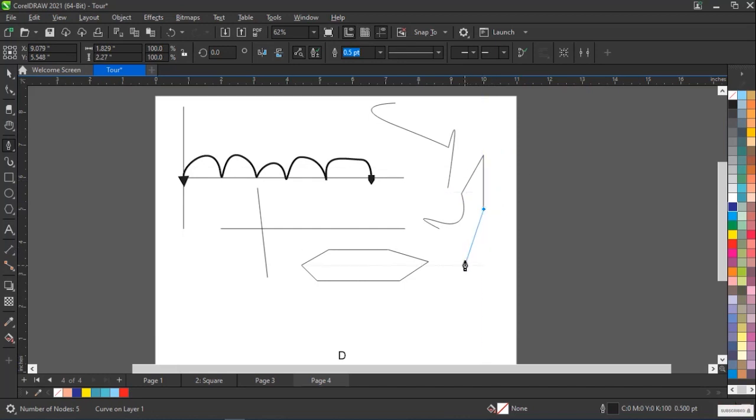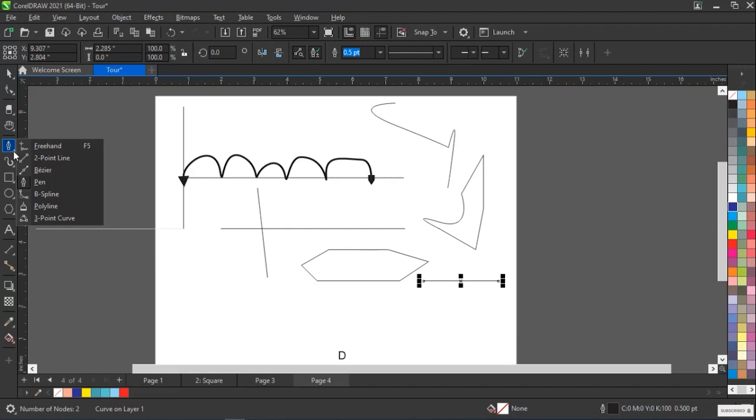Now the difference between this pen tool and the Bezier tool is just when trying to use a Bezier tool, you don't see the line. The lines you're making are not visible, but pen tool will have to show you the line and the direction it's going to go when you click on another point. So as well, you can use it to make a shape of your choice. You can as well use it to make a line, a straight line, or anything. So whenever you're done, you have to double click on the last node to drop.